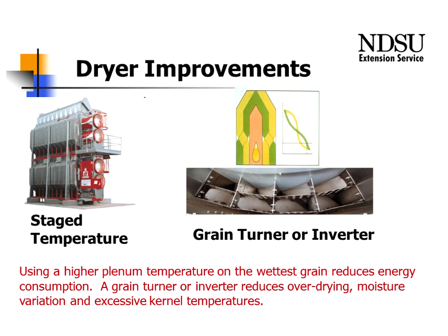The stage temperature dryer, here we're doing essentially the same thing that we were doing with the 2-heat dryer. We might be running the top dryer up here at a much higher temperature without damaging the corn quality because of the evaporative cooling. And then the lower portion of the dryer, we back off on the temperature so that we don't damage the corn quality.